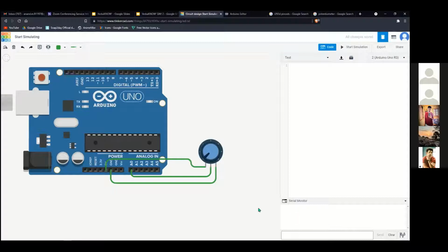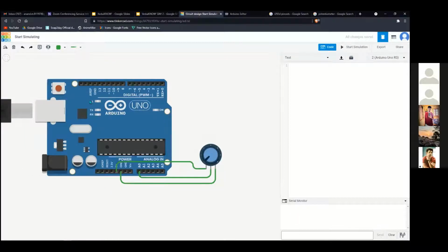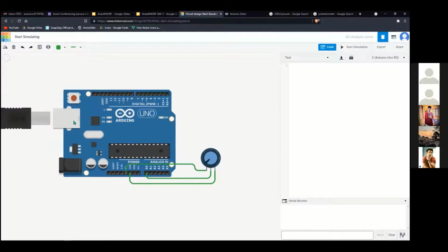Basically, you might know that in order to program the Arduino, you need to connect your Arduino to your laptop or a PC system. Once you connect, your Arduino will establish a communication with your laptop or CPU. So once you open the serial monitor, whatever data is present in the microcontroller will be transferred through the USB lines to your PC, and the PC will process it and display it in the serial monitor. So this is basically a software based debug.